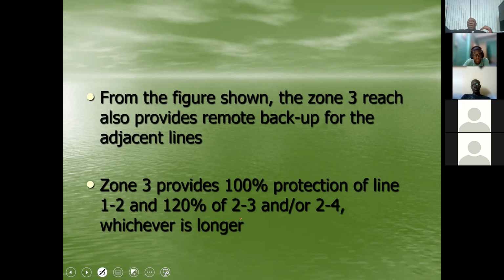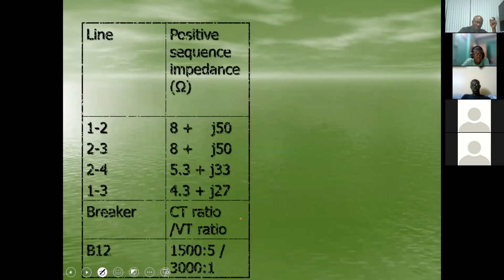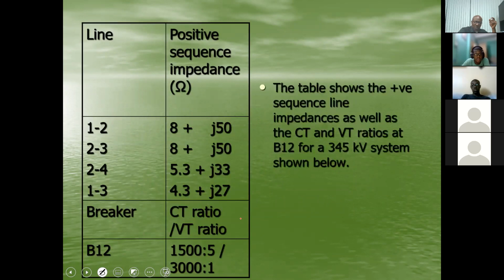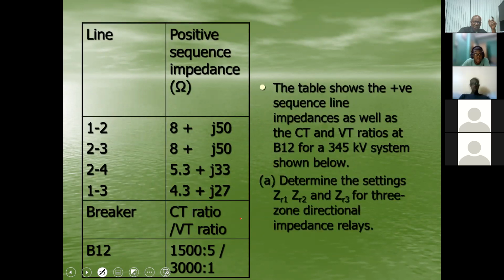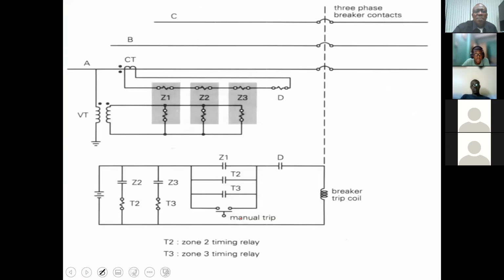So you're going as far out as possible on zone 3, which means that the delay on this is going to be even longer, because by putting in the zone 3 time, you're giving the impedance relay on 2 lines down the road the chance to operate, if that is indeed where the fault is. All right, I'll come back to that. We'll go through that another time.